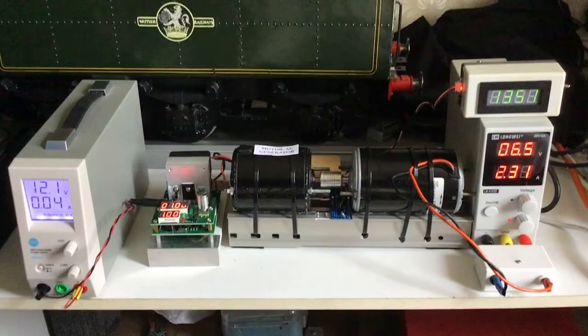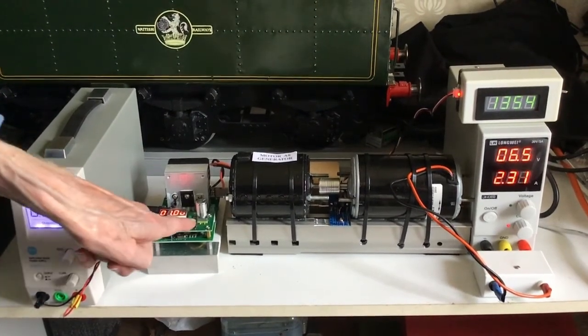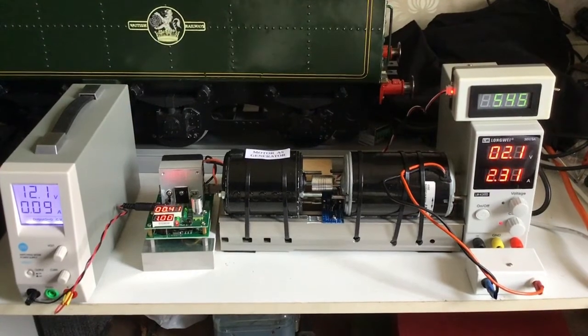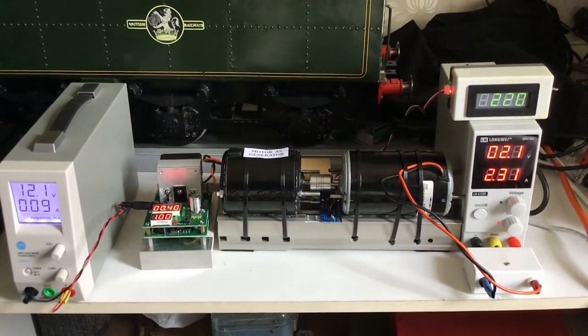The previous setup can demonstrate this. The motor power supply is now used in constant current mode, and with difficulty has been set to 2.31 amps. The consequent voltage drop across the motor is 6.5 volts, and the speed is 1351 rpm. When the 1 amp load is applied, the speed collapses to 219 rpm because the system cannot call on more current to balance this additional torque load.